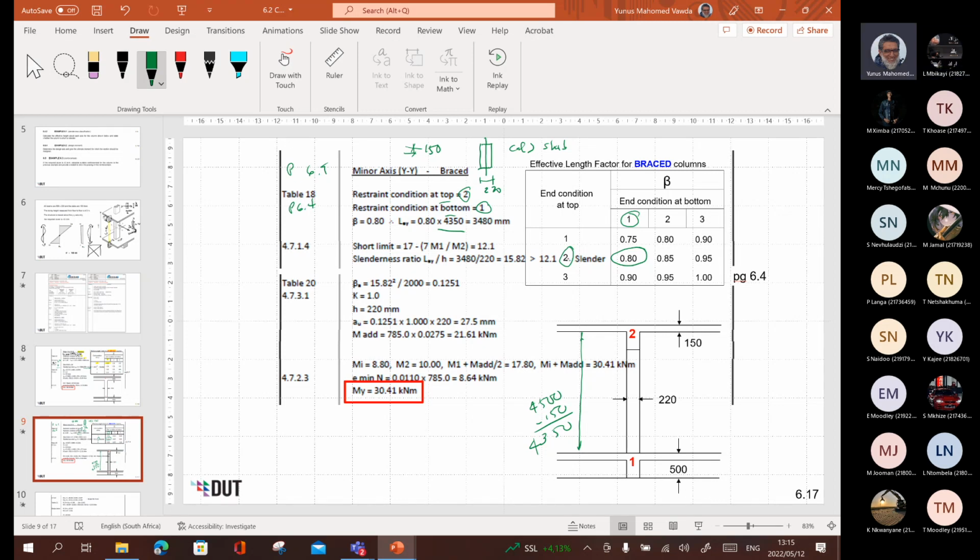From the column it looks like it's two-way, but it may be that there's a beam somewhere else in the slab which we can't see, further away. So we don't want to make assumptions about the slab span right now, because we don't have the full picture. Without the picture, we can only go by what is given to us in the section. There's only a 150 slab there. We're not concerning ourselves right now with the span of the slab.